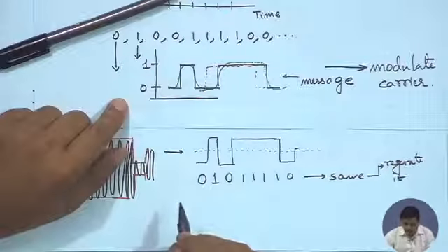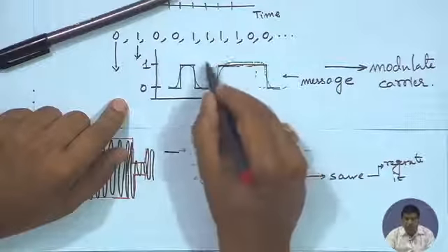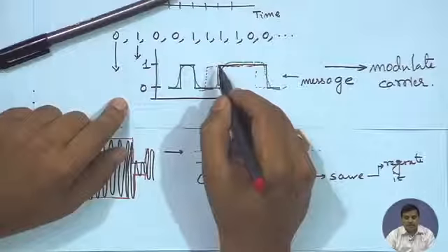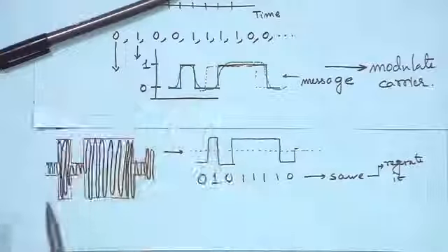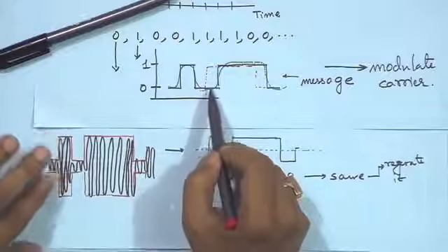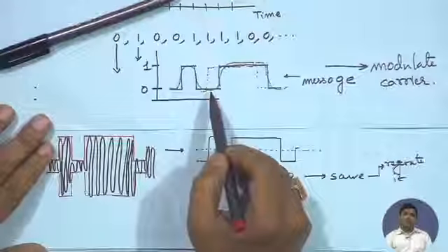In analog communications, this distortion is almost impossible to correct, because you do not know what is going on, you do not know what the message is, because this message is generated at the source. If you knew the message which is to be sent, then you would not send the message. That means if I already know what will be sent to me, what is the need to send that message? So at the receiver we do not know the source message a priori. So this particular mistake will not be captured and it will be used as it is in analog communication.